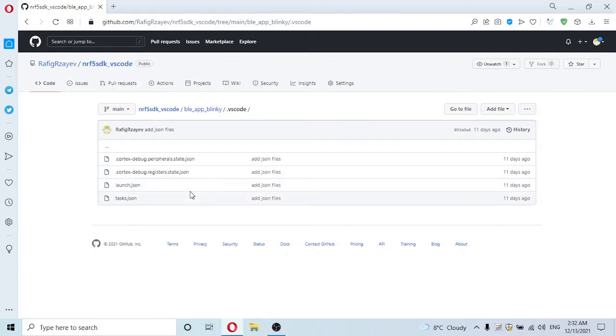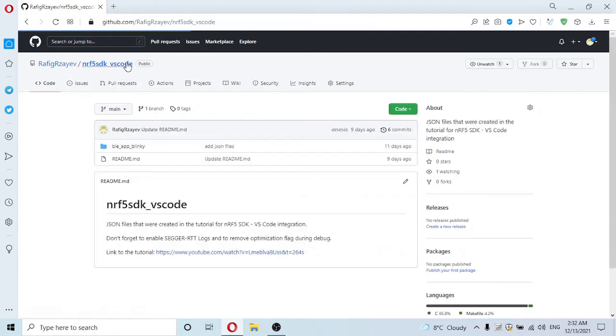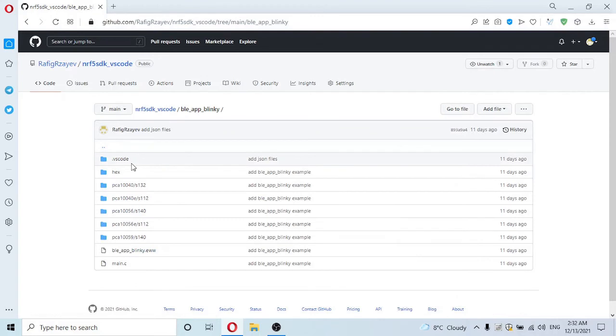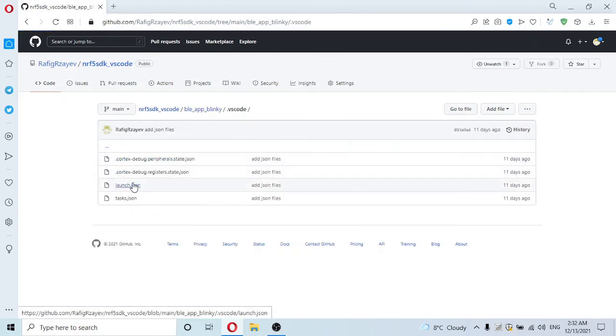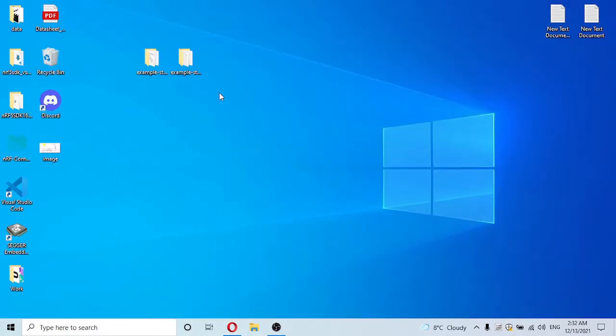You can find it on my video channel, but this video is long. So what you can do instead, go to this repository here, nRF5 SDK VSCode. Inside it, you can find the folder called .vscode. It has several JSON files, and we will move this folder into our project, and that way you'll be able to debug and see the logs.